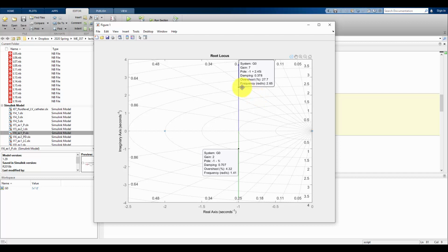Now we're going to see how we can modify the root locus in subsequent examples, but here, these lines are again showing me, up to 15 at least, all the different poles that I have to choose from. I can't choose anything out here or in here because those are not appearing on the root locus. There's no amount of gain that I can pick that's going to let me pick from those poles.